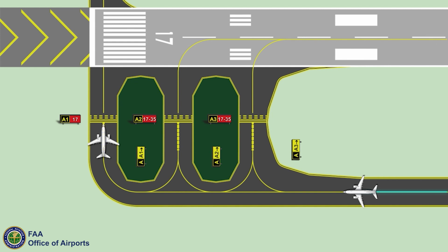This improved holding bay design channelizes taxiing aircraft by providing individual bypass taxiways with no taxi islands. This configuration allows for standard elevated runway hold position signs and edge lights, and enhances pilot situational awareness.